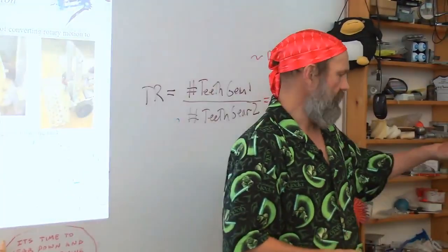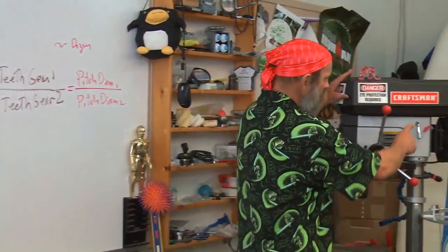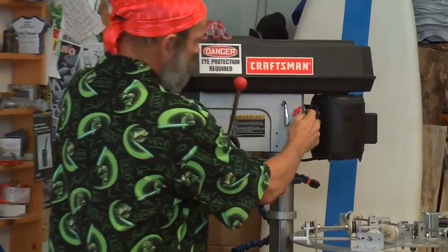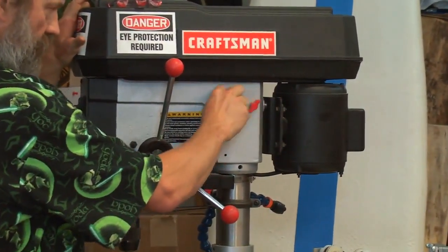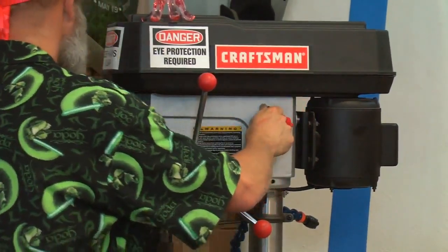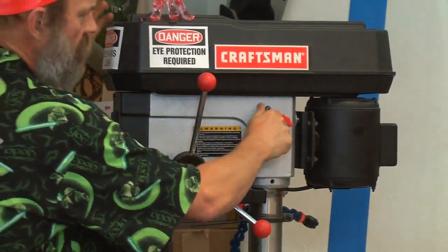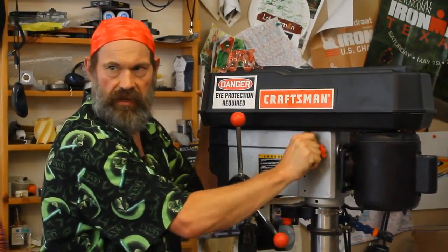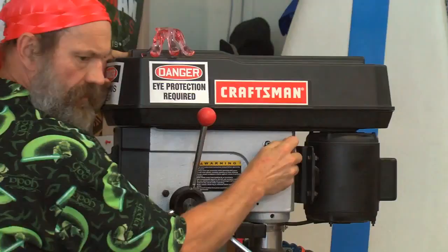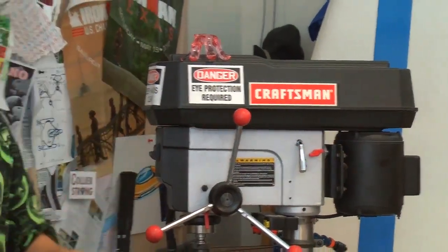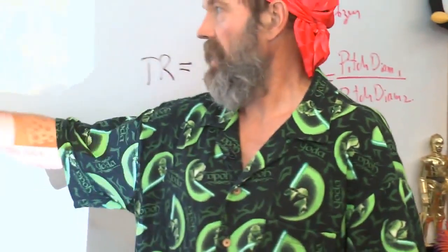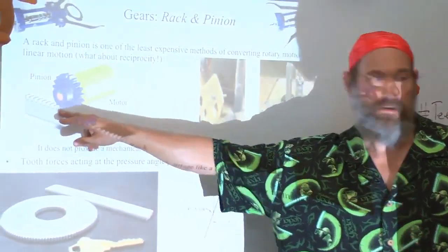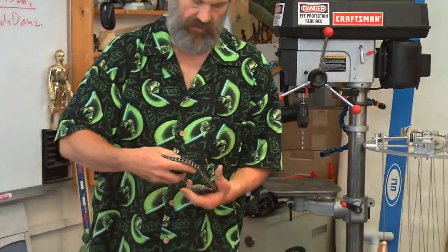Remember, the rack and pinion is something that you can't see it in here, but the shaft that holds the motor has a rack surface on it, so when I turn the handle, I can get linear motion out of the motor to tighten or loosen the belt that's inside. You can make a rack and pinion by having a rack that you've bought or water jet cut or machined. You can also lay down a chain. Remember our discussion of chains.